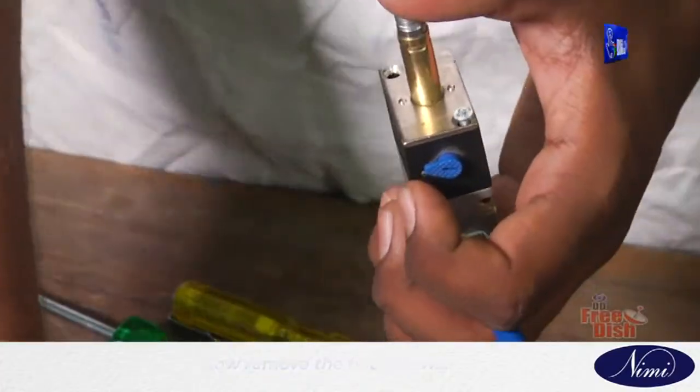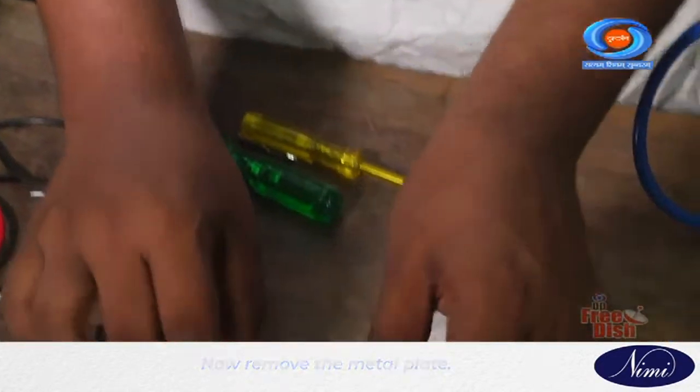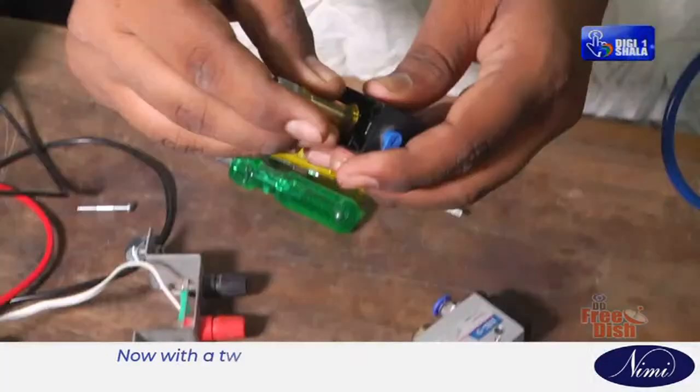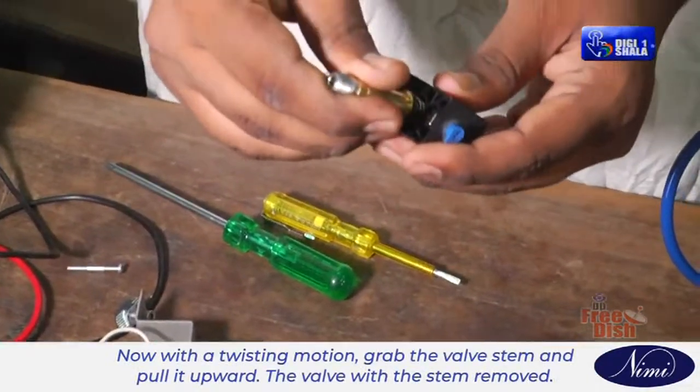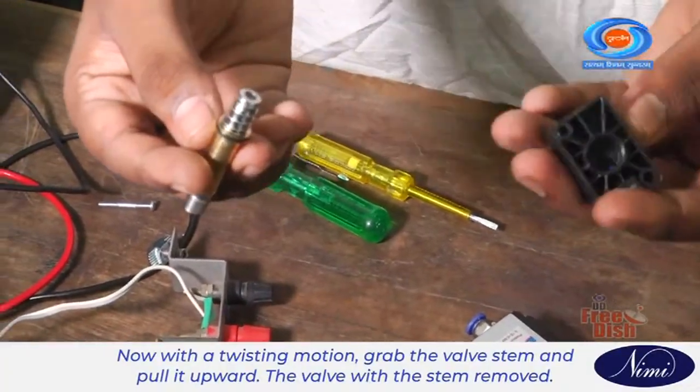Step 4. Now remove the two screws. Step 5. Now remove the metal plate. Step 6. Now with a twisting motion, grab the valve stem and pull it upward. The valve with the stem removed.